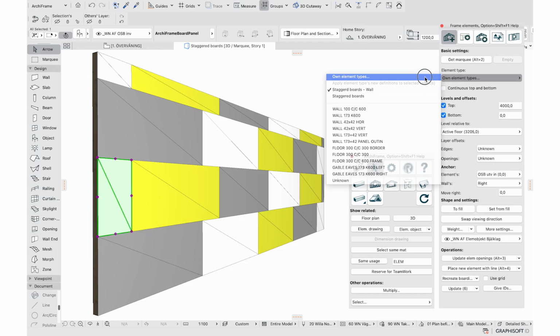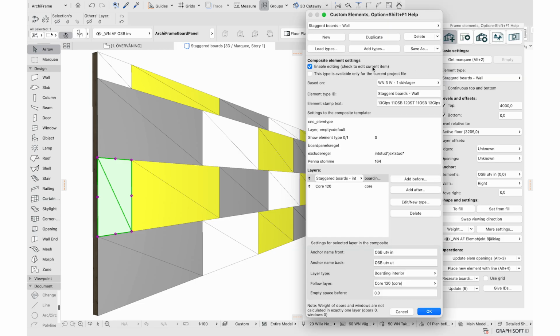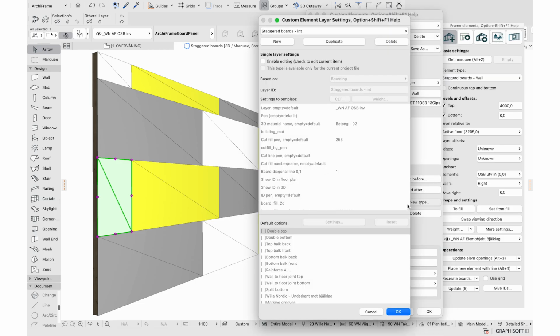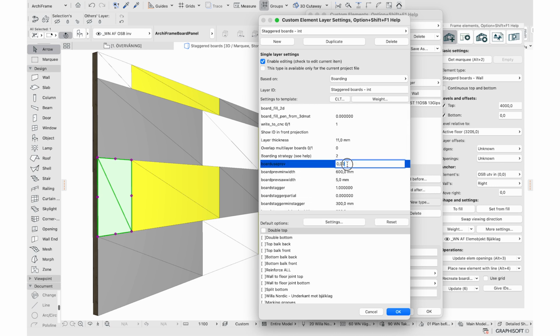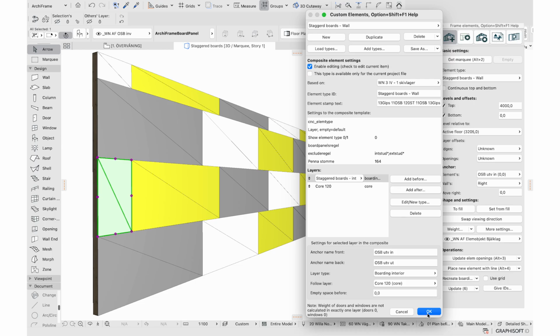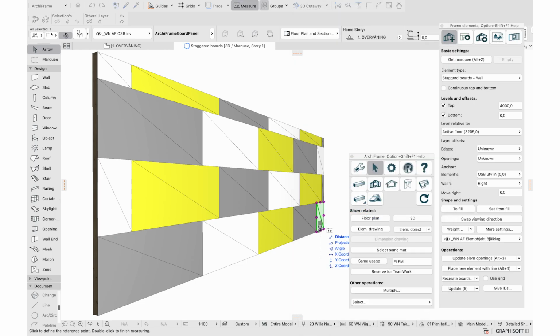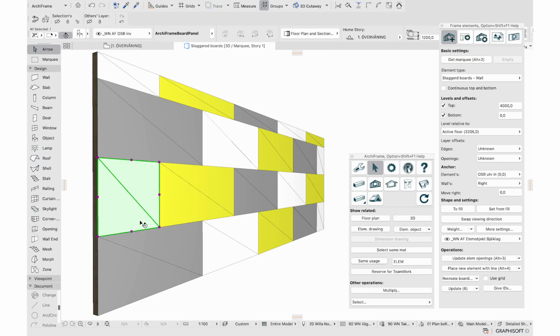It's also possible to use the remaining part of the last cut board, as long as the given minimum size for it allows. In this example, the last board width is less than 1 meter. Since the boards are 2.4 meters long, the remaining piece is wide enough to span 2 column widths, 1.2 meters.